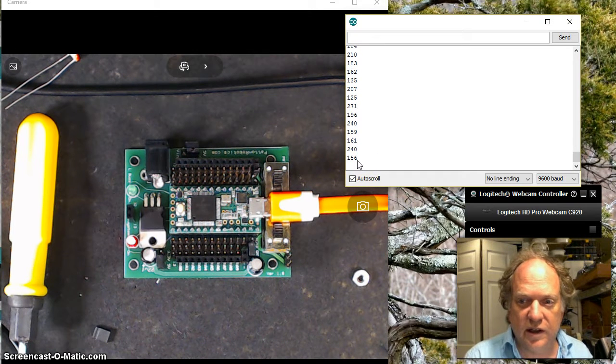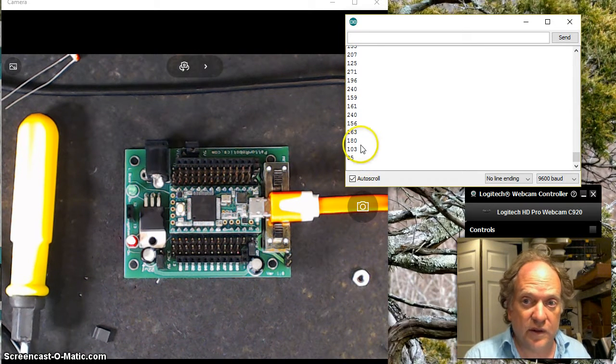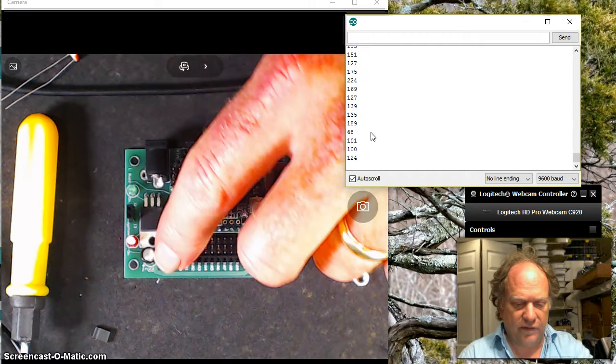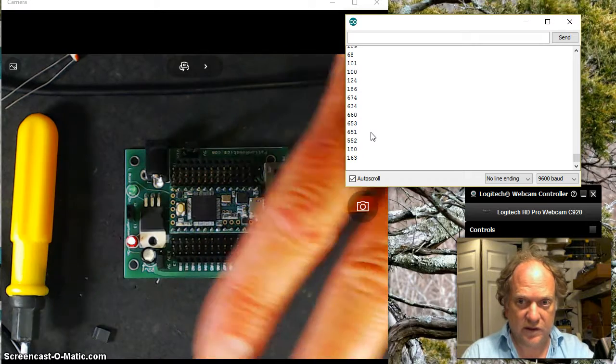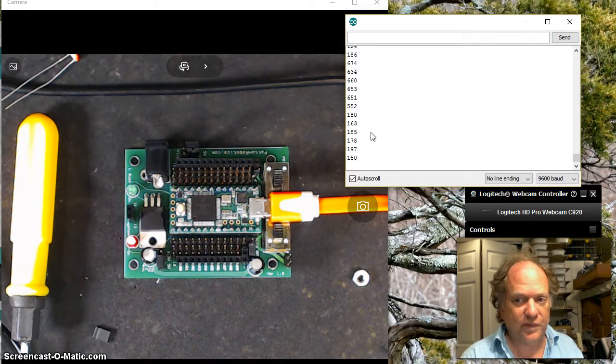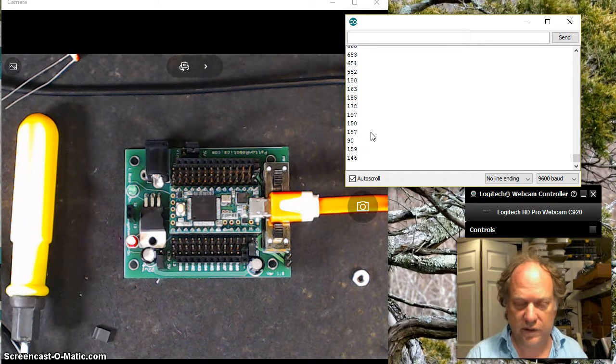It's amazing. We can't choose the scale, but the numbers are anywhere from the 80s to well over 200, averaging maybe around 150 to 224. There's really no predictive pattern. In fact, if I touch it, it'll probably change. It probably depends a little bit on the humidity of the air and a number of factors, and it's always going to change. It's always going to drift. It's a floating pin.